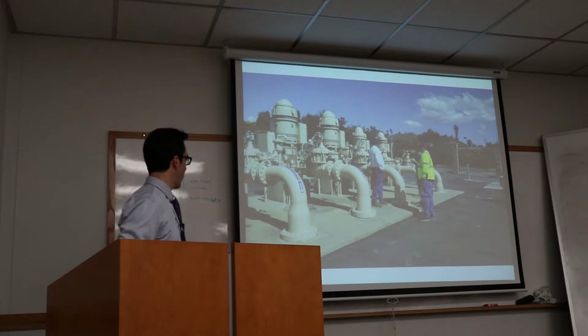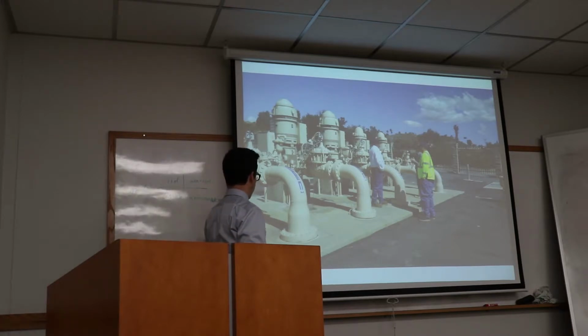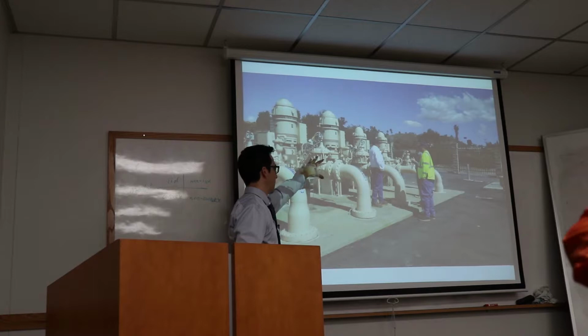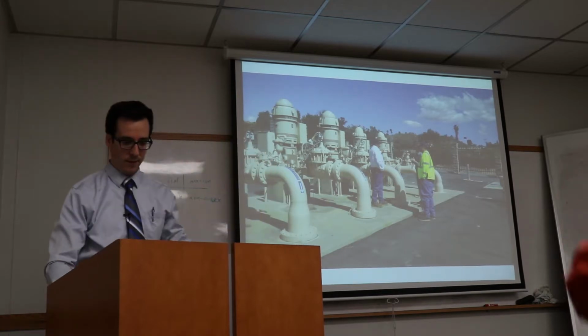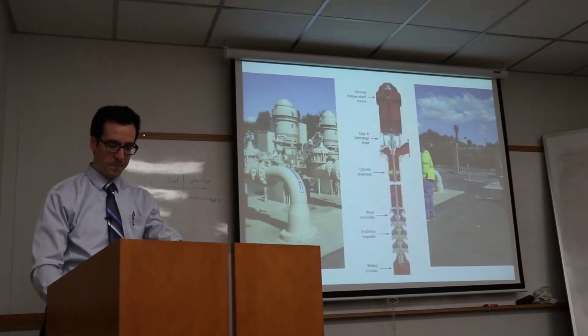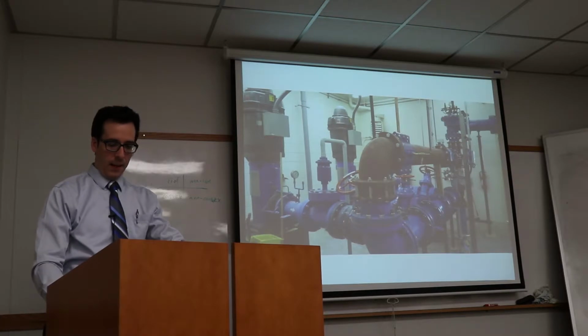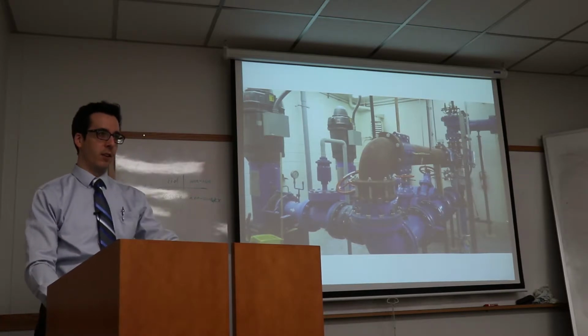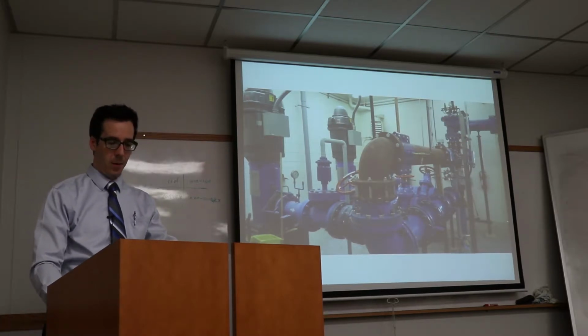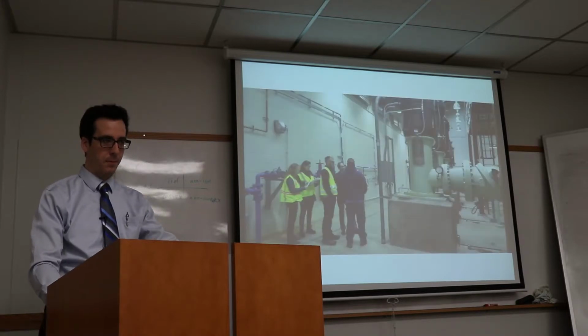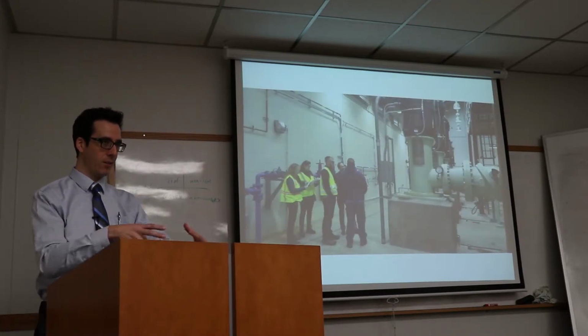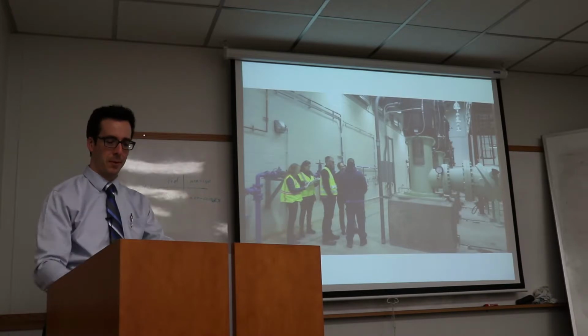And so in this case, water is coming up through pipes in the ground, up through the turbines here, or the impellers and the bowls. It's driven by the motor and then discharged to this side. And this assembly here is a control valve. Some other monitoring equipment. So again, a lot of what you'll see will be these vertical turbine pumps with the line shaft driven motors. Smaller pumps will be like the first one we saw, where it's a horizontal, inline centrifugal pump.